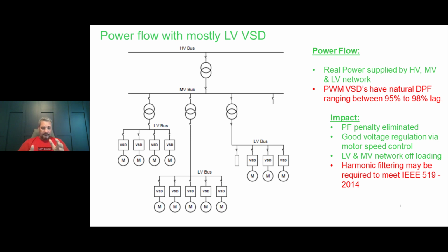Then another issue you have to be concerned about is to control the amount of harmonics being injected by these VFDs. So it becomes more of a harmonic filtering issue than power factor correction at that point.